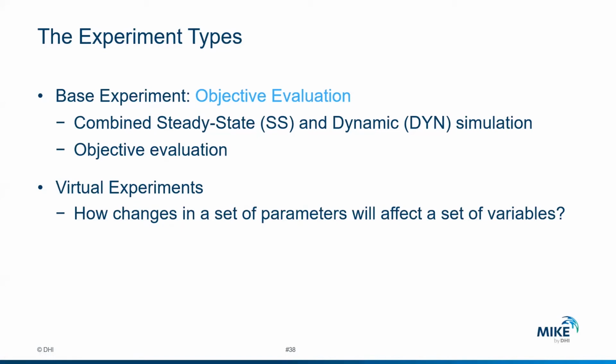So you can define a complex objective that could include indices in relation to the effluent quality, the energy consumption, the sludge production, resource recovery, whatever, all combined and weighted in an appropriate way. And then you can characterize one simulation with one number, with one objective, and on this ground you can compare different scenarios, different setups. This is the base experiment.